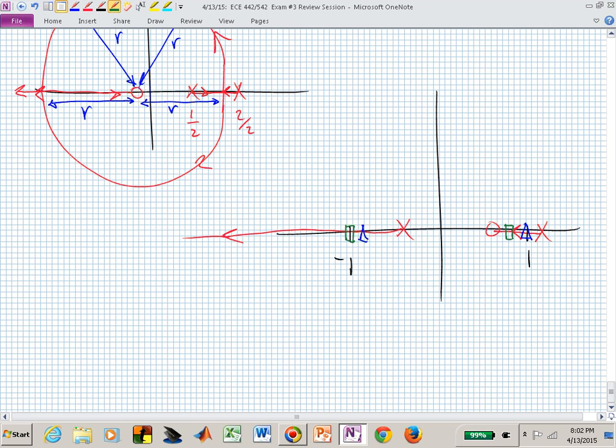What you're not hoping for is that the triangle on the left is to the left of -1 when the triangle on the right gets to 1. If that's the case, then is this system stabilizable with a gain? No, you can't stabilize this system with a pure gain controller. Is that clear? How you could determine that from just the pole zeros and where they're located?